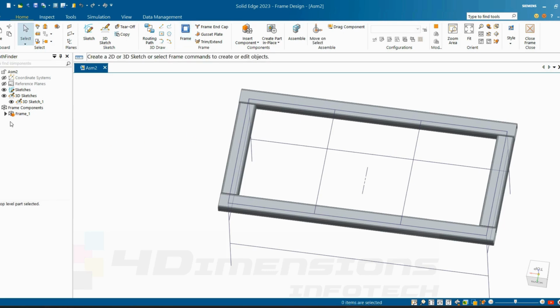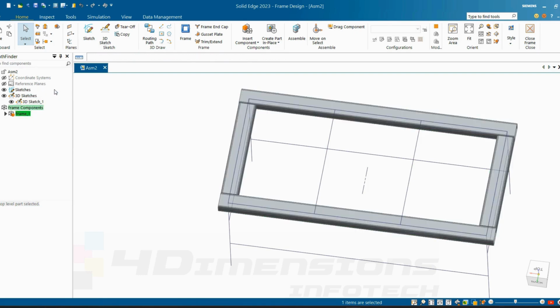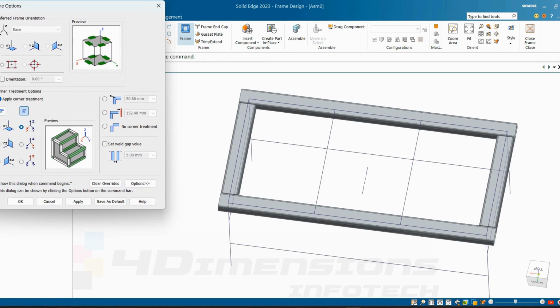Say finish. If I want to change the end condition and reverse the conditions here, I want to make this vertical tubings overlapped and this horizontal tubings underlap. We'll go for the option and select again the end conditions option. As soon as this frames option appear here, we are going to change the axis system. At present this axis system has been activated. You can see this blue colored icon. I'll click on this option. After clicking, you can see here the orientations are being changed.